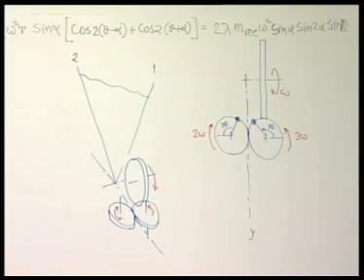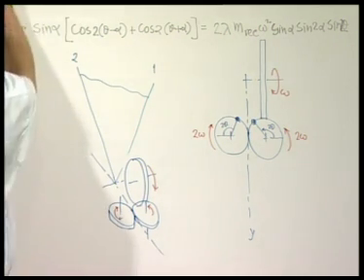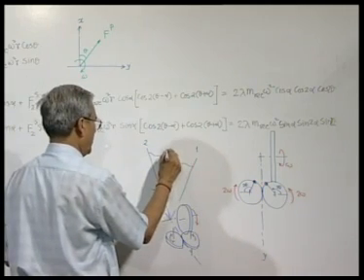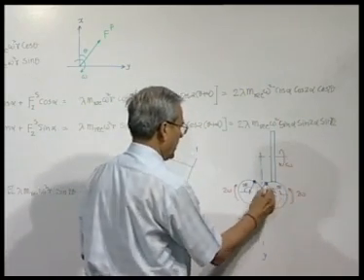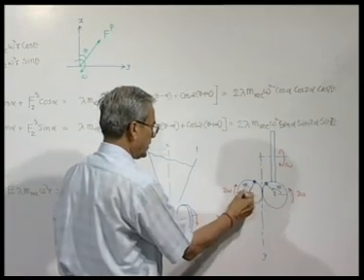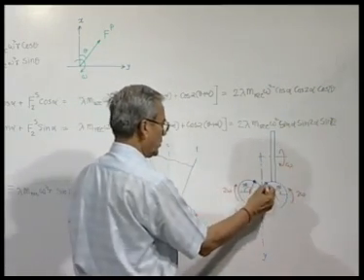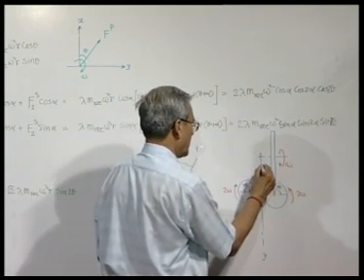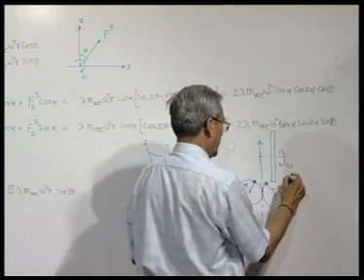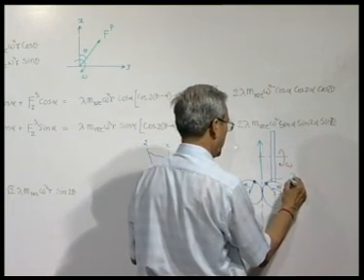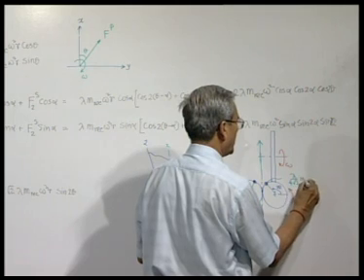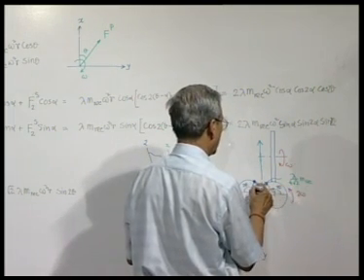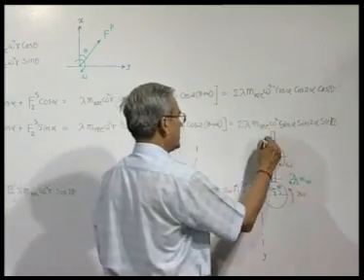Now, we have placed two unbalanced masses in such a manner that when theta equal to 0, that means when the common crank is along the x axis, then the two masses are here. Now, since it is rotating at double the speed, the angle they will make with this direction will be 2 theta in both the cases, and the amount of unbalanced force they will generate, if the two masses are lambda by 4 root 2 m reciprocating and r, this is r. So, this force both of them will generate.